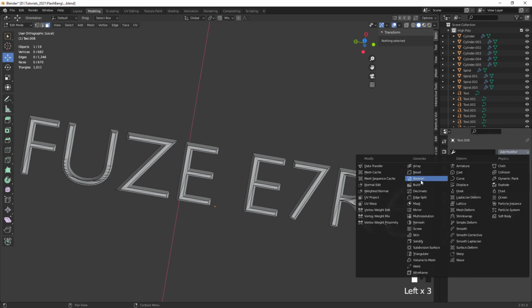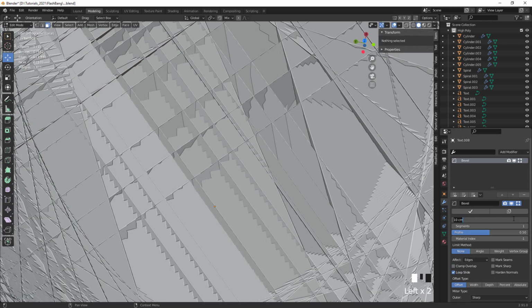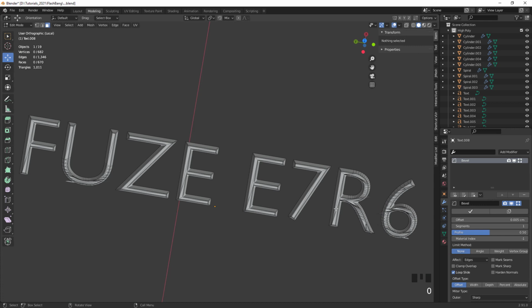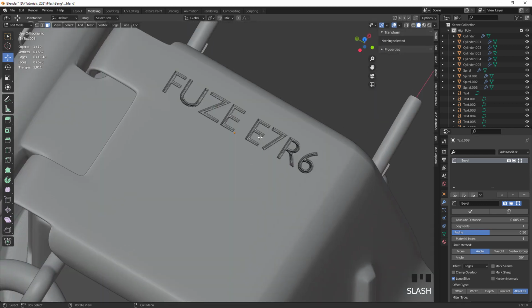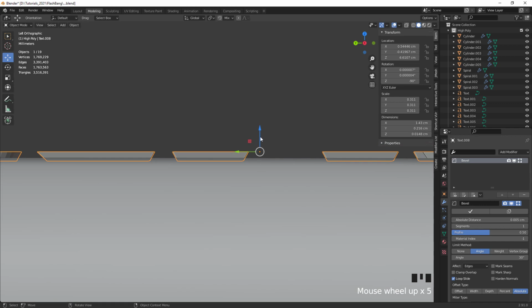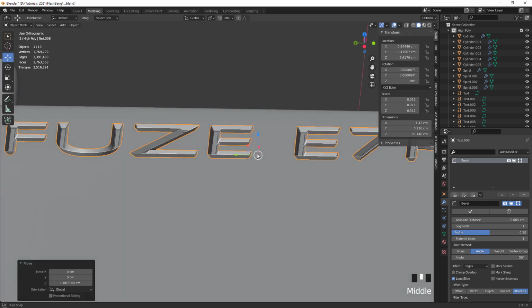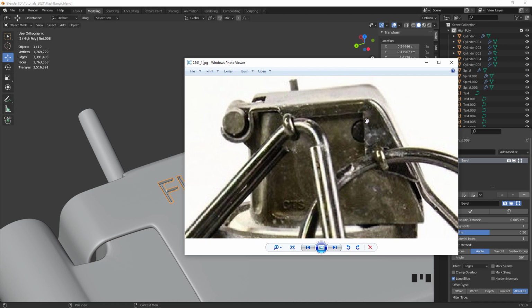And now in order to make it a bit more high poly, we can just add a bevel modifier. Gonna disable clamp and put this to a very low threshold here, 0.005. And that looks weird, but if we check it over here to angle and absolute, now you can see that we don't have these weird pinches, so that should look fine in the high poly. Even if you see some weird fragments, don't worry about it. This is engraved in there.